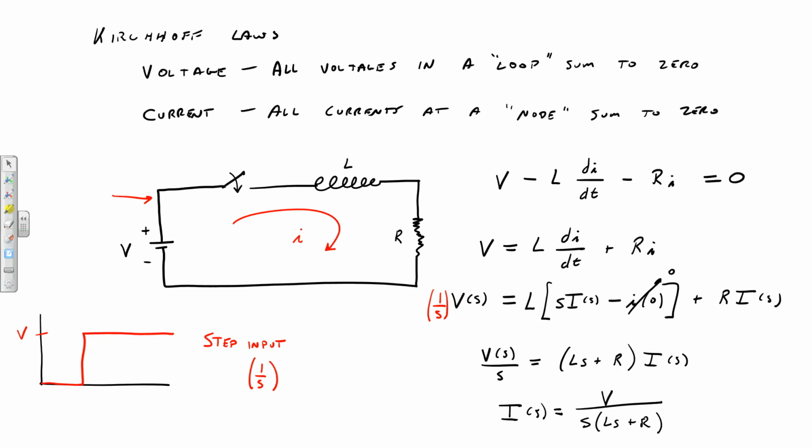But right now we're just focused on this. We can create the transfer function. And yes, I'm starting to think about inputs. We're going to look at inputs, unit impulse. We're going to look at step inputs, the unit step. Will we look at anything else? A unit ramp, I suppose. A ramp is just 1 over s squared. So we'll look at some of the basic inputs there.